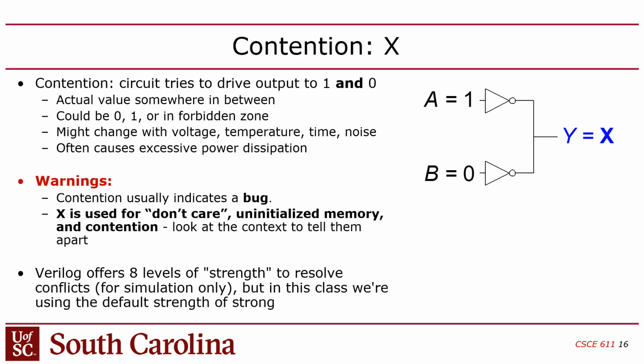So in order to detect that kind of condition in your digital simulation, you have to associate a third value to the binary data type, and that's called X, contention. If you simulate your design and you see X's in there, that could mean you're double driving a net, double driving a voltage. Makes sense? That's actually a very common error in this class. You'll see that a lot.